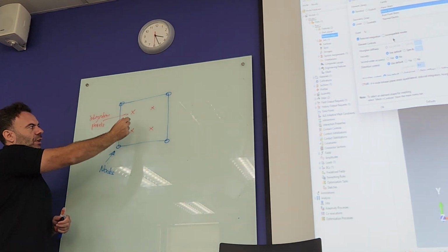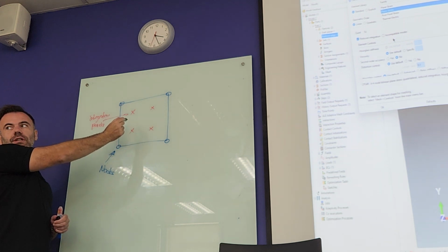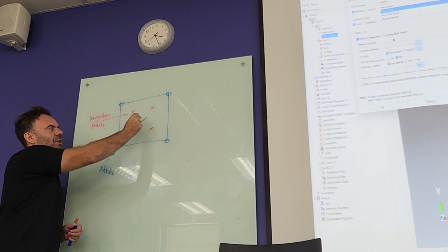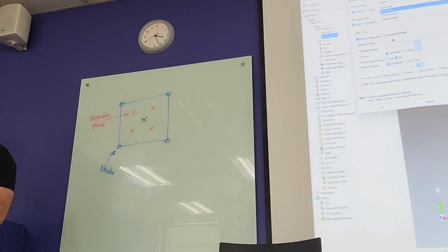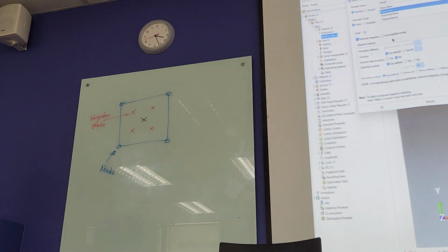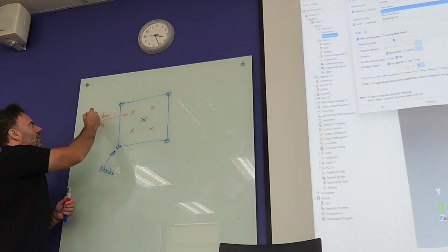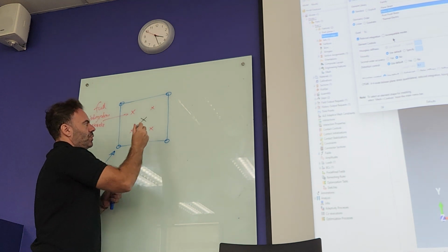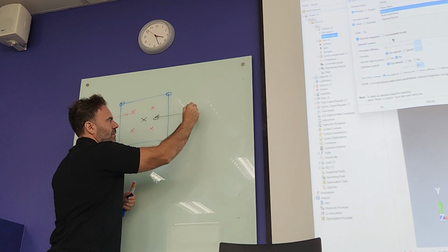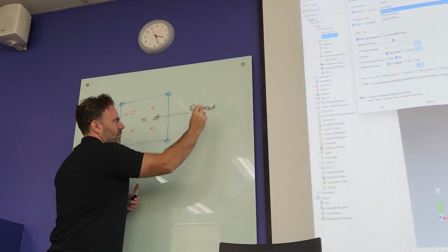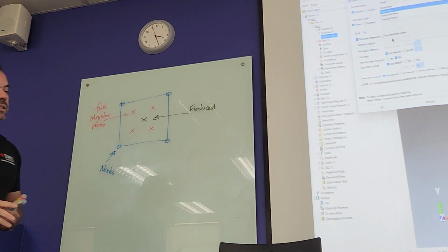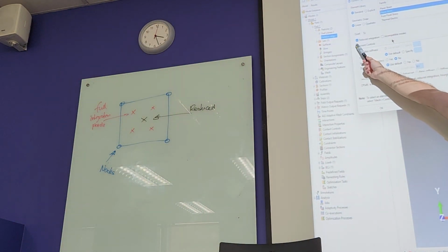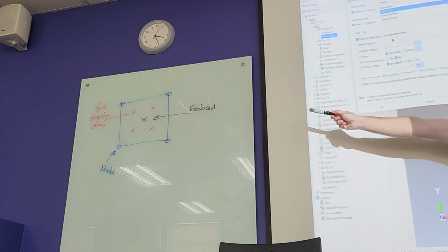So it goes through in Y as full integration, 1 chops off in that direction, 1 chops off in that direction. Basically, you end up having 1 in the middle. So that is full, and this is reduced. By checking that box in or out, we choose how many integration points we have.